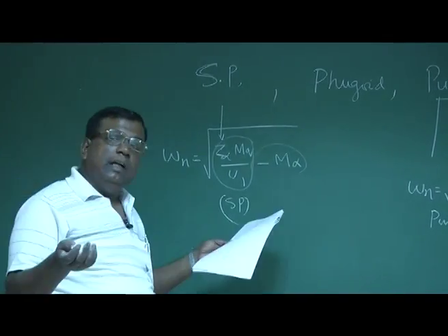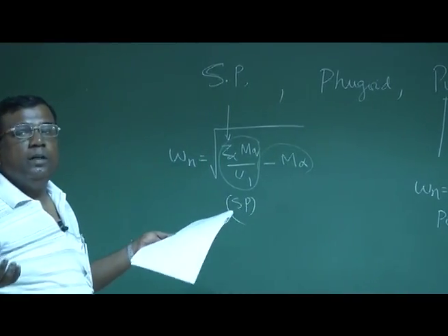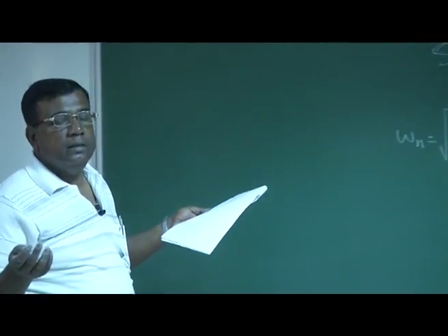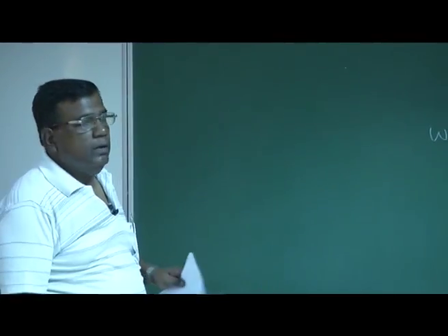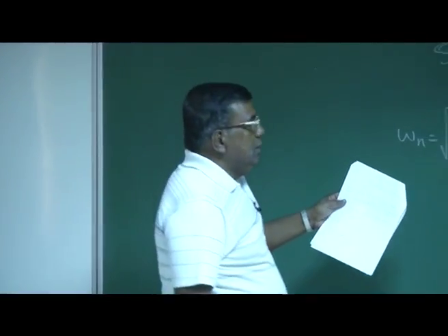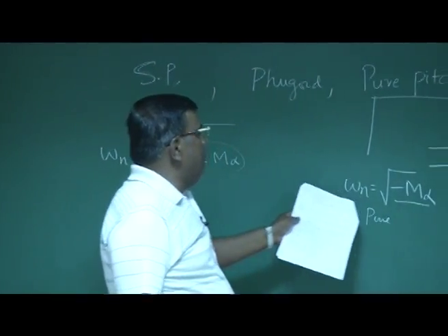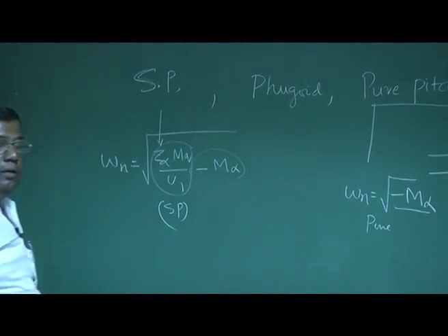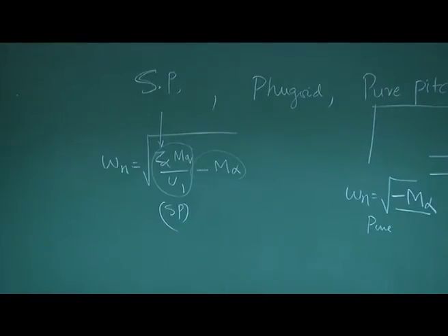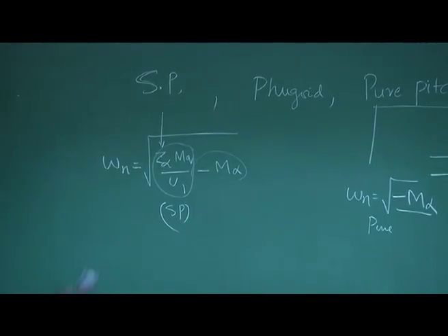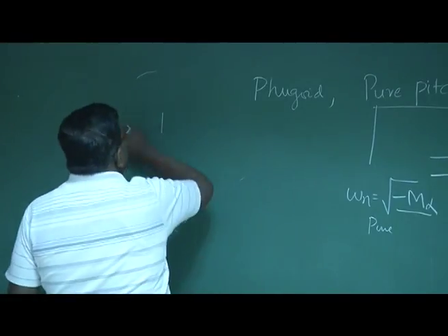And then I come to the dynamic stability in terms of A s^4 plus B s^3 plus C s^2 plus D s plus E equals 0. I solve that whole equation. So this is the simpler route. Go from here to here, then go to that big equation. Okay. So today I thought I will share with you something called stability augmentation system.